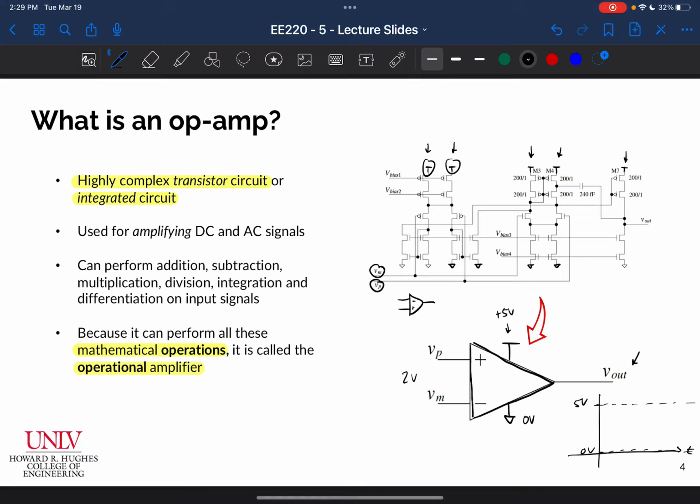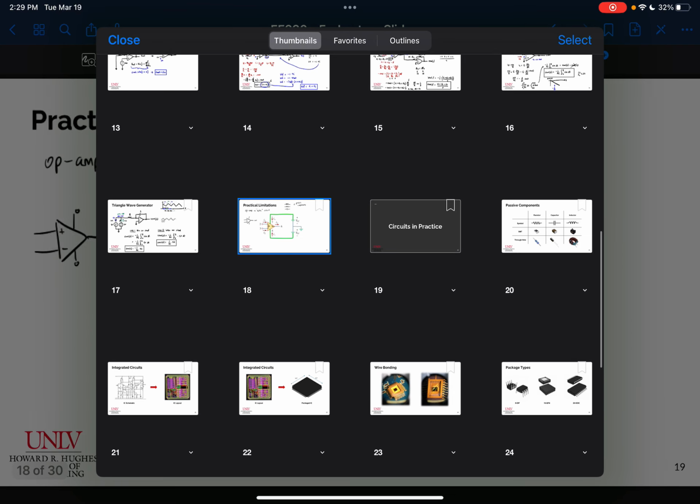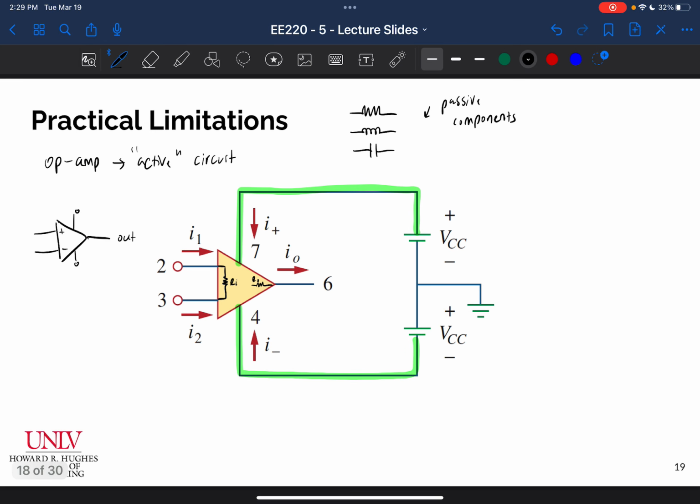Okay, so let's go back to that slide now that we're on. It is here. And so you can see that in the op amp, they're telling me, oh, I'm going to supply a plus VCC to this top. Basically, that would be my positive supply rail, and then this bottom one is my negative supply rail because, you know, from 0, this rail is at VCC. If I go across this one, I'm at minus VCC.